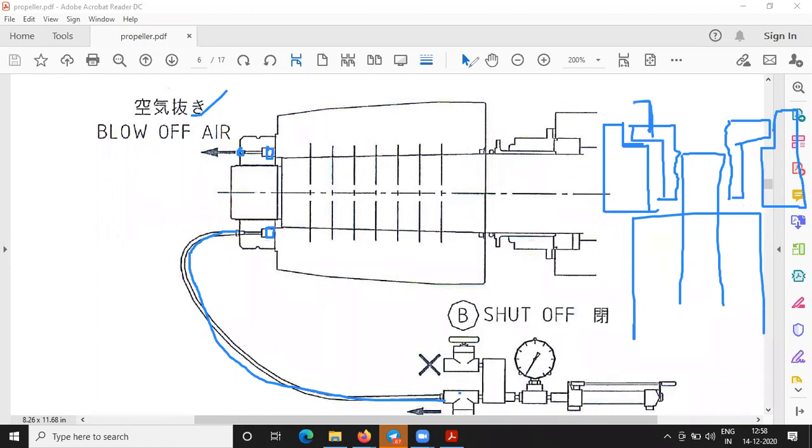As we start giving the oil pressure, initially, whenever you give the oil pressure, will you see the deflection in the pressure gauge directly, or will it take some time to reflect the deflection? It will take time, sir. It will take time. Why will it take time? Because first the oil has to fill all the recesses that are there, and as the liquid is incompressible, when the pressure starts building up, this portion of the hydraulic jack starts moving up.